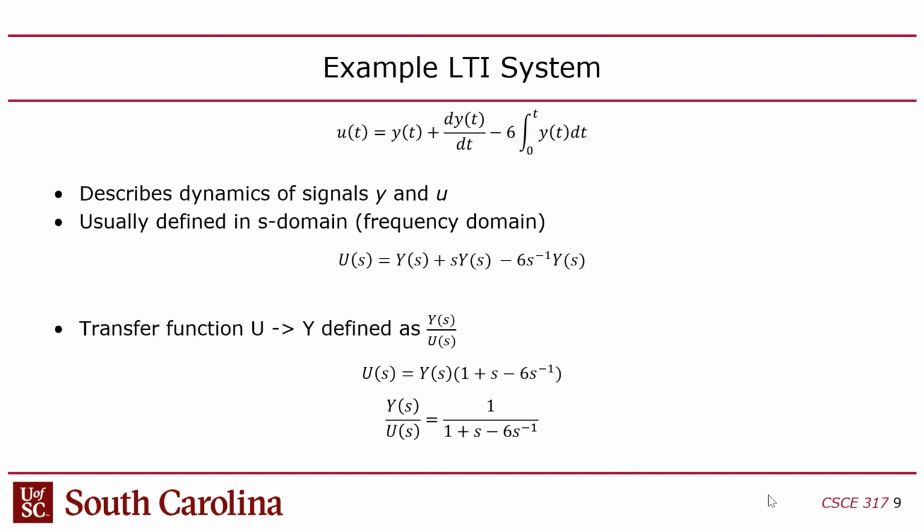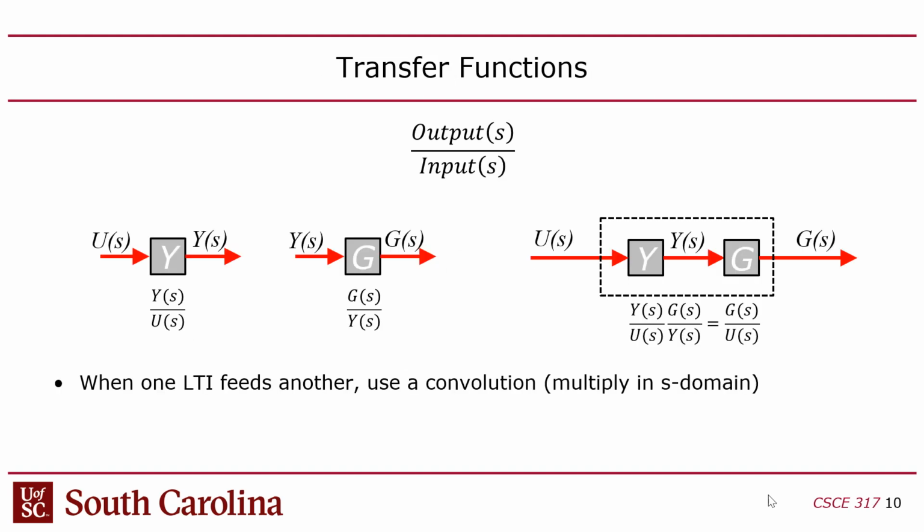Okay, so now you might say, well, what's the point of all that? The nice thing about these transfer functions is they're composable. So if you have a transfer function, this ends up becoming like a block diagram editor, like in a CAD tool, where you can take a transfer function and you can connect them together like building blocks. So you could take one transfer function and another, and you can feed the output of one into the input of the other. And when you do that, you get a new transfer function that is simply the product of those two.